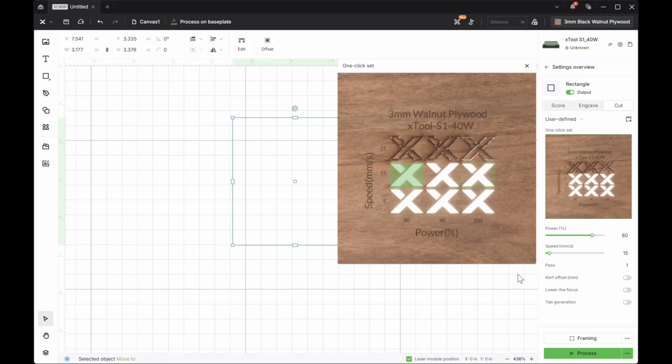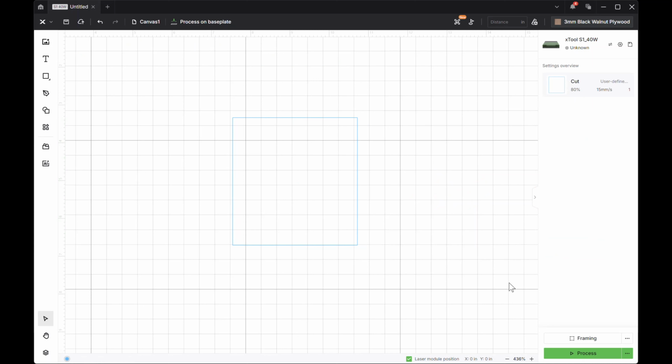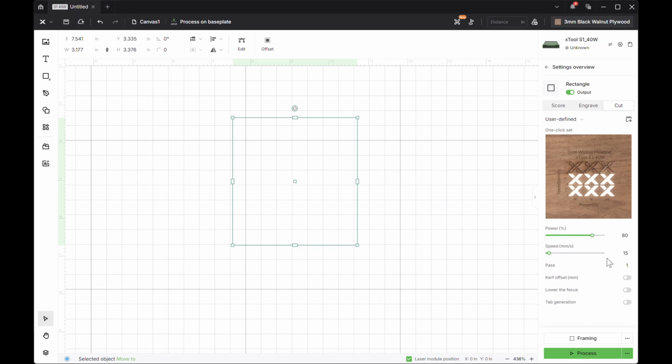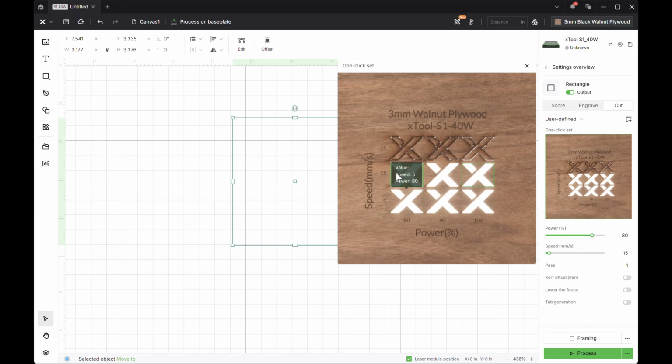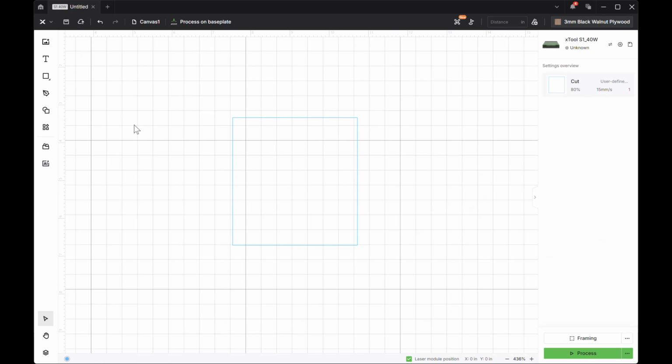The lower that you get your power and your speed, and it's going to be successful, the better. All right. I'm just going to let you know, because if you're going to run your power at 100 and your speed very, very, very slow, like this, if I could run the speed at 100, right? So power at 100, speed at 15, I can't. That doesn't make any sense. But if I could do it at 15 and 80, I'm still going the same speed, but I'm actually getting the same, looks about like the same output. So that's what a material test array helps you with.